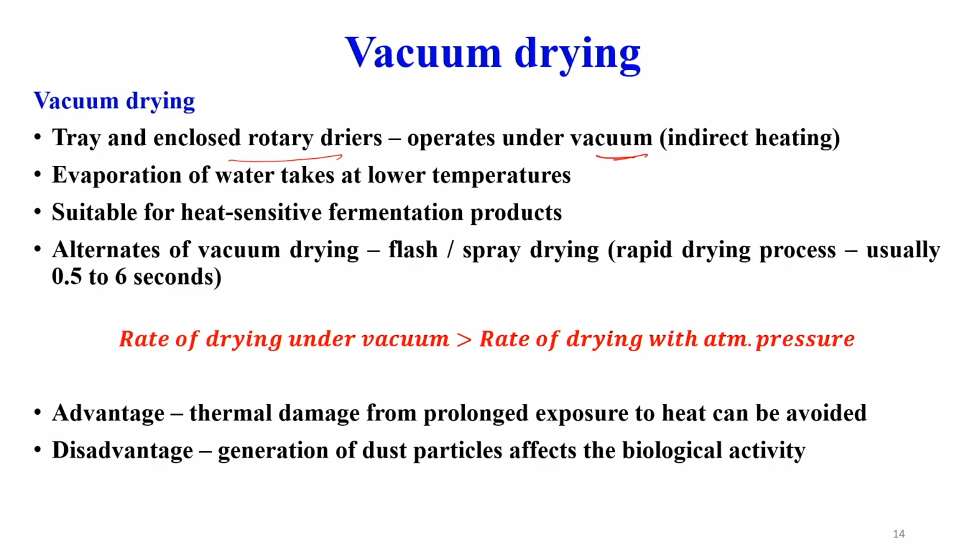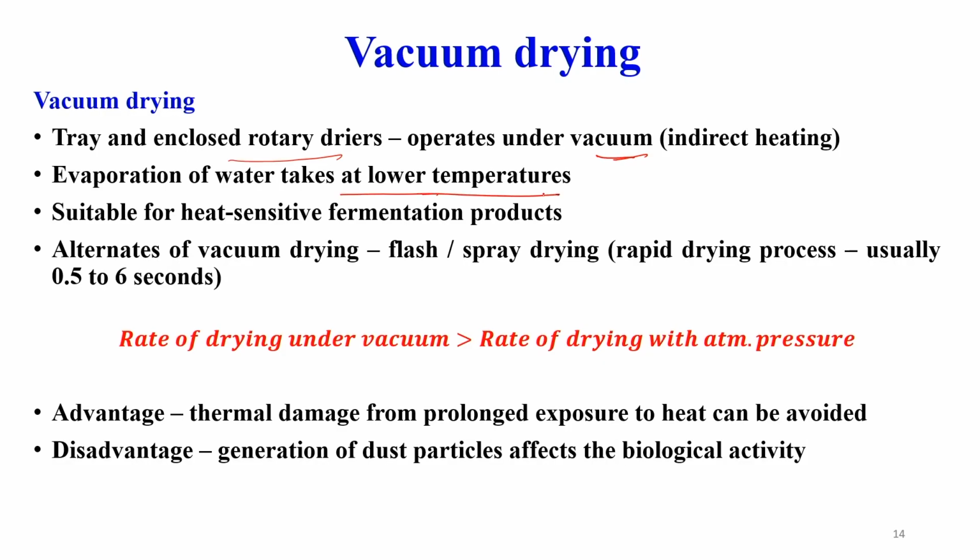Now, typically what happens is, if you increase the pressure, the boiling point of water increases, and if you decrease the pressure, the boiling point again decreases. So, under vacuum it evaporates even at a lower temperature. So, evaporation of water takes place at lower temperature because we are lowering the pressure, and this is suitable for heat sensitive fermentation products. An alternative to vacuum drying can be flash or spray drying.